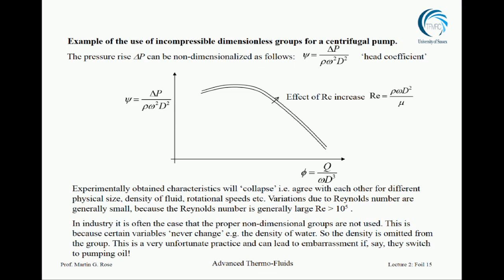You'll see the curve has a broadly straight region at high flow coefficient where the pressure drops off steeply as the flow goes up. So you can imagine that the faster the flow goes through the pump, the lower the pressure rise. This is what we call a stable characteristic, and it's what we want. This is where the pump will not do anything funny and get into trouble.